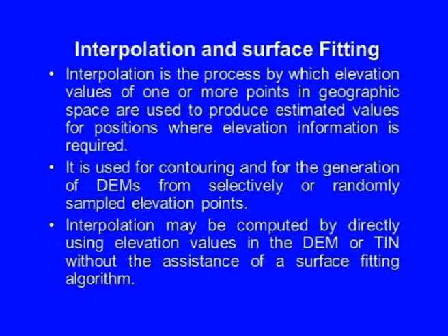Interpolation is the process by which elevation values of one or more points in the geographic space are used to produce estimated values of the positions where elevation information is required. It is used for contouring and for the generation of DEMs from selectively or randomly sampled elevation points.